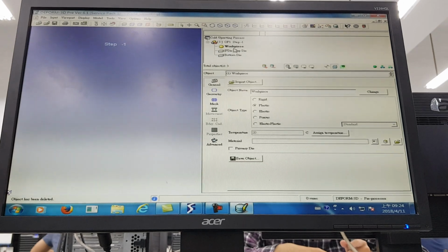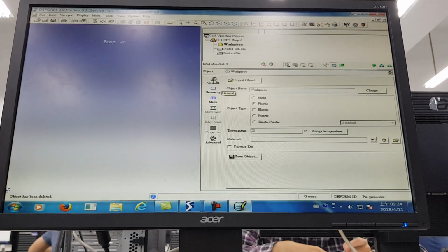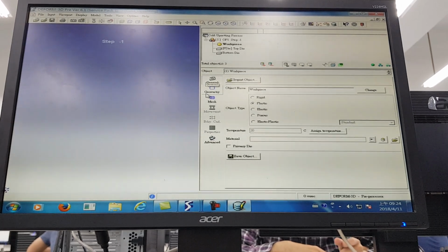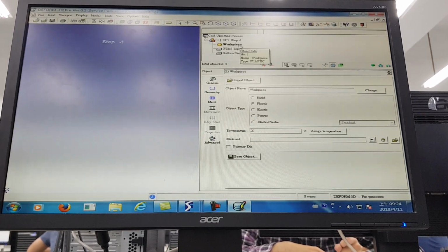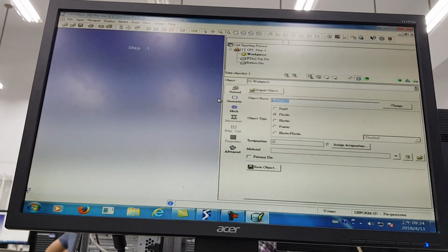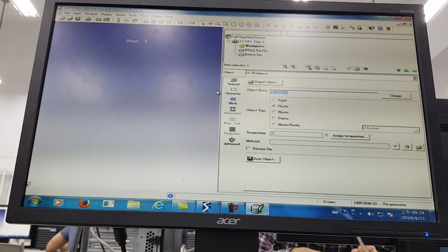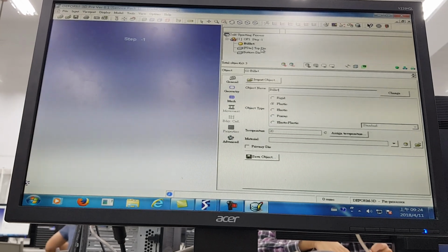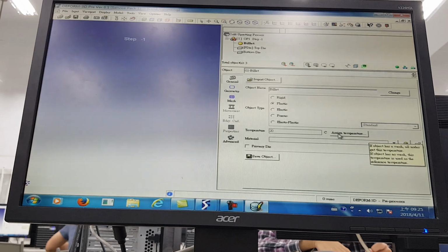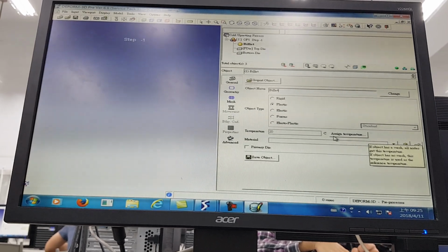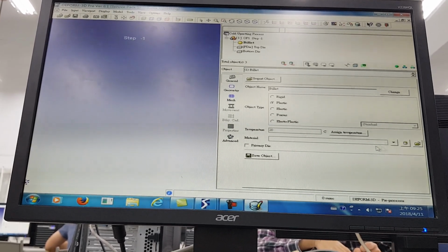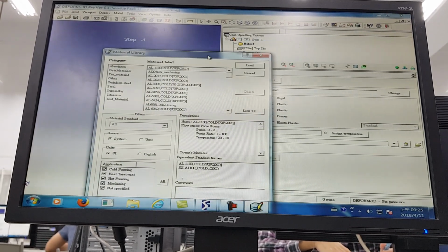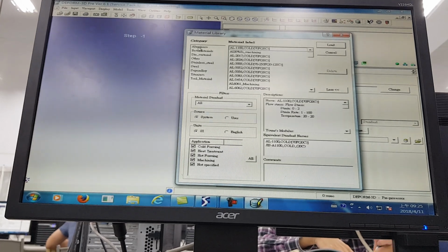Okay, right now we need to select in here, always from up to down, and your setting is always from up to down, left to right. Okay, in workpiece, for me, I will change the name. I will call this Billet, and for your cold upsetting process your temperature is 20 degrees, and right now you need to assign this Billet their material.